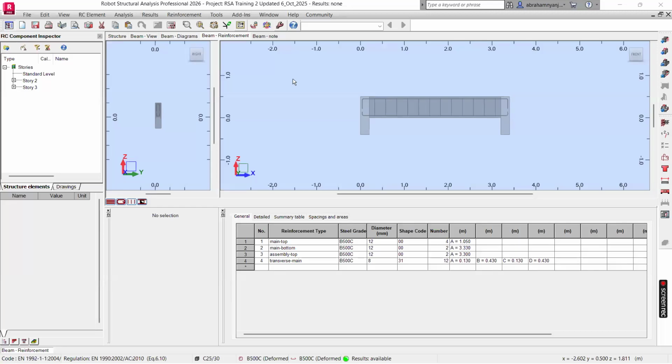When it is empty, it will only be the self-weight acting. So that is the assumption: if in my load combination I capture the worst case scenario and the structure stands, it will stand even if the tank is empty, or halfway, or a quarter.